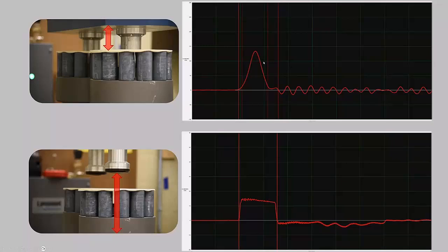But that's the two impacting surfaces that give you this short duration half sine shock pulse. And then this setup is basically trying to show you that the plunger with the nose piece on the bottom of it goes down inside the piston and hits the top of the piston. And then you get what are called square wave or trapezoidal waveforms.